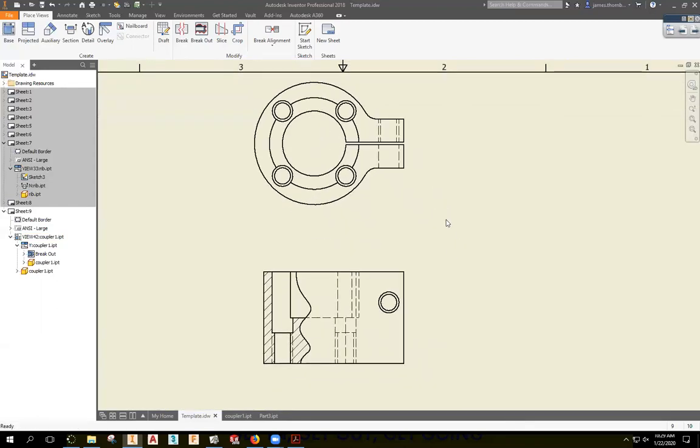Okay. And then kind of figuring out stuff. So this hole, this circle here, so these two circles, I could do it a hole of the counterbore, right? If I care about how much space is here. If I care about this space, then I can do a diameter and I can actually dimension that space. If I care about this bottom space, I have to have a section or something to see that. If I care about this top space, then I can just do it from the top view. Okay? So figure out what you think is best.